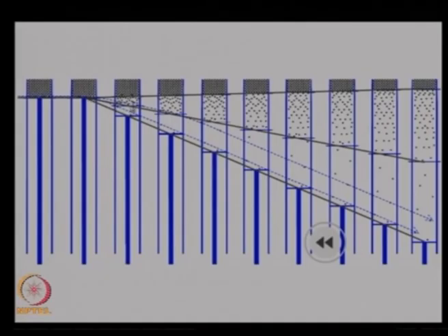It is going through the expansion like this, stretching inside, and the gap is increasing here, and finally it will come out from here, and then you can again see the particle moving at a constant velocity parallel to the wall, if you imagine the 2D case. It is just at a constant distance from the piston, which means the relative velocity is 0. It is moving at the same velocity as the piston in this region.